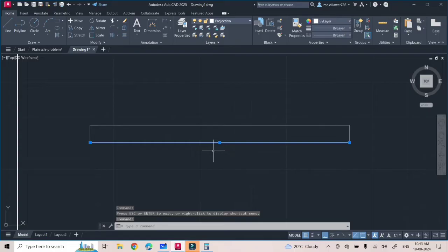Simply click on this line, then the division command, DIV, enter. Then you need to click on that line. If I say click, it will always be a left click, right? Left click only. Then next, for the number of equal parts, you need to type 6, then enter.